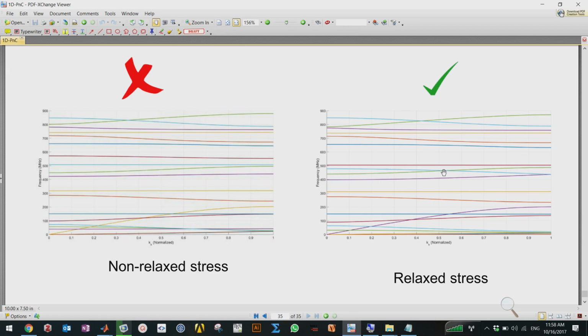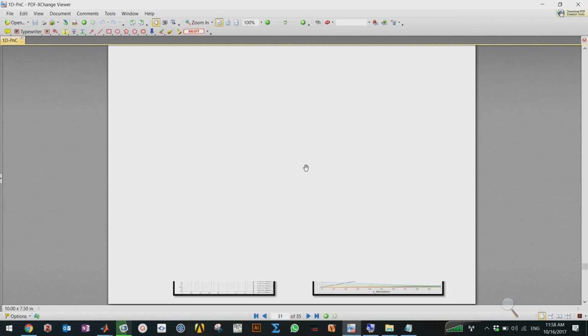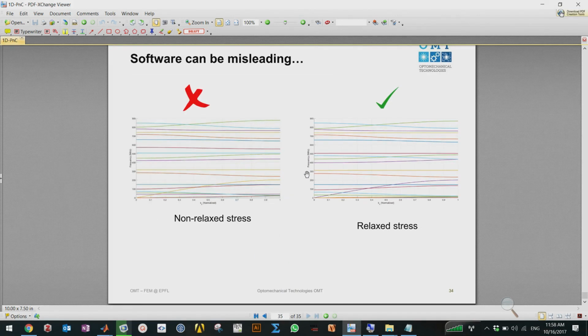I was just wondering why you use fixed boundary conditions and not rolling, because now you hold your beam at a fixed. Yeah, because my beam is doubly clamped from two sides, and I want to see how the stress will relax when it's clamped from two sides. That's the case, your beam is clamped from two sides. But it gets thinner, right, also on the sides? It can be, yes, true, but here I'm just simulating one unit cell. That's true what you're saying.